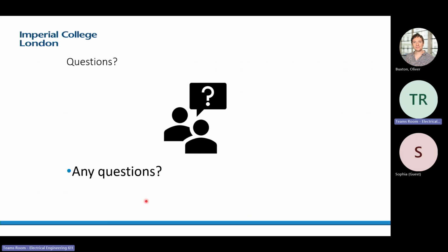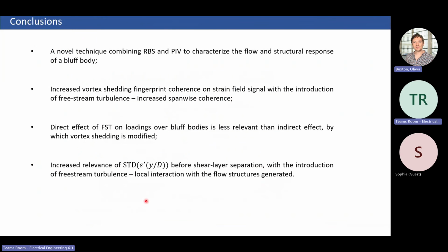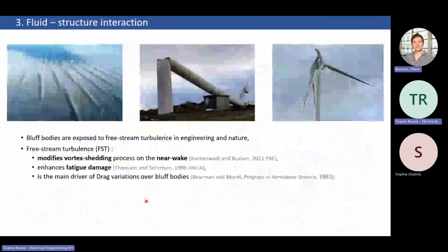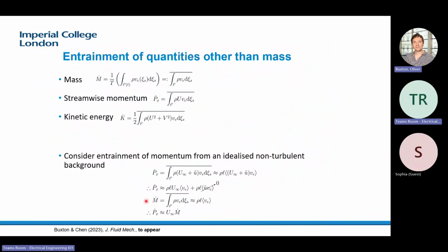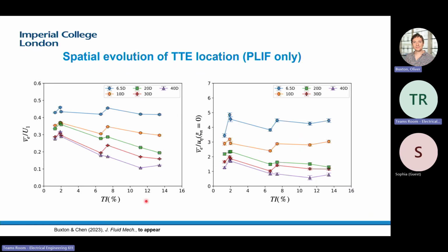Of course, yeah. So the first one is about the turbulent entrainment. Generally, wake models state that the more turbulence intensity we have in the inflow, the higher the rate of expansion of the wake. The main reasoning is that turbulence intensity in the inflow enhances wake mixing, so the wake spreads faster. Yeah. You are stating the opposite.